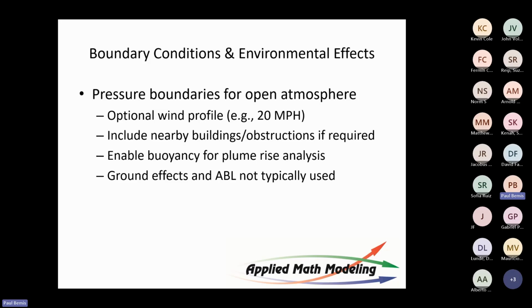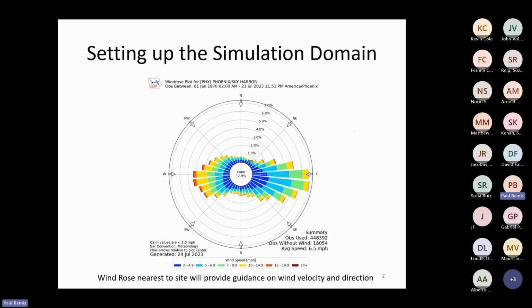But we generally don't include it here because it's not that significant. We're only talking about buildings that are 30, 40, 50 feet. The air is generally uniform up there. Let's put it another way. When we've used velocity curves based on height, it doesn't change the output very much. It's kind of the same. So we don't generally use them, nor do we use temperature. Temperature is sometimes varied as a function of height as well. As you know, the upper atmosphere is colder than it is down on the ground. But in a building of 30, 40, 50 feet, you're not going to get that much temperature delta. So they're there, and they can be used, but generally not a big effect. They're a second order at best.